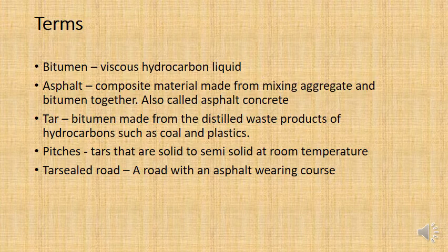That's bitumen. I'm sure you've all seen it, and it's very black and very dark. Now, asphalt, that is a mixture of bitumen with aggregate. So you've got to remember the difference between asphalt and bitumen here. It's a little bit like concrete. Remember, concrete is distinct from cement. Concrete is a mixture of cement with aggregate, and asphalt is actually a mixture of bitumen with aggregate, and that's why historically it has been referred to as asphalt concrete. These days we just say asphalt.